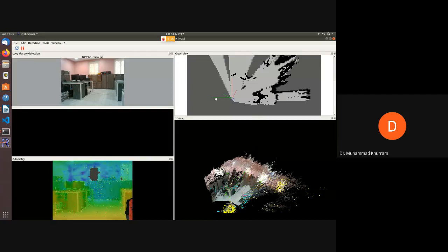So what are the features? Now we are coming to the sensor's raw values. These are the values that a sensor utilizes to identify its environment. These are similar to the point cloud that is being generated by a LiDAR. For each pixel value, the sensor is returning a distance value in a 3D space, and we are utilizing RTAB-Map, which is a library of ROS, to grab the sensor values. And right now we are just mapping those sensor values in a heat map sort of positioning.